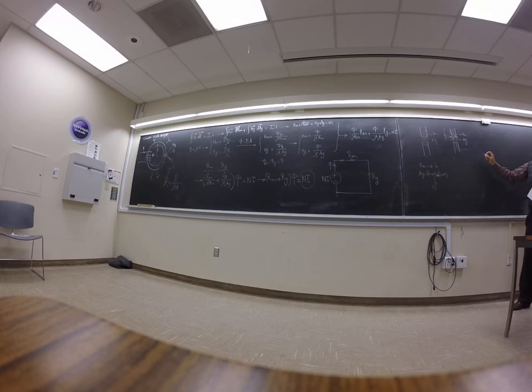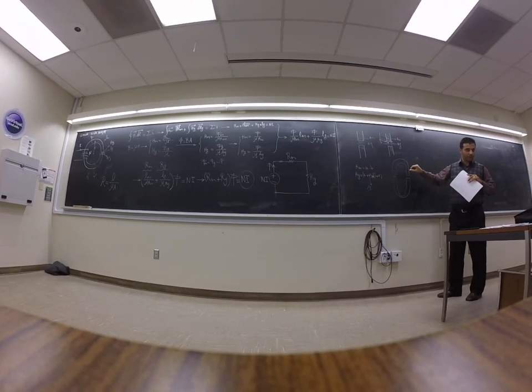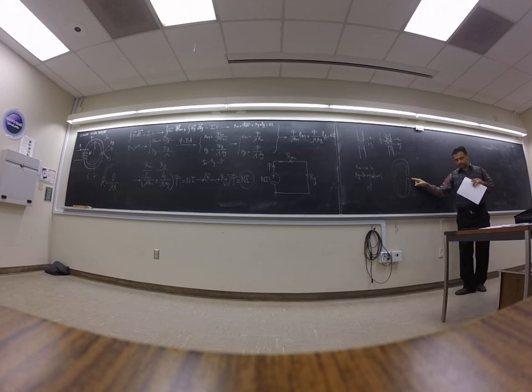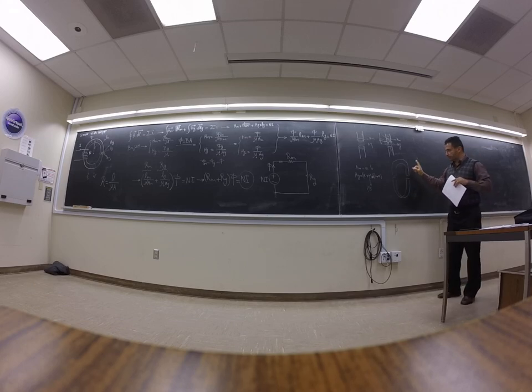The core we used was a C core. C core is like that. So we had something like this, 2 C cores. That was one design. I'll bring it to show you guys. It took 3 months of heavy finite element calculation to get to this. This was the core we had, and we calculated the loss. There was a copper loss because you have a winding, and there is a magnetic loss. So we calculated for this one.